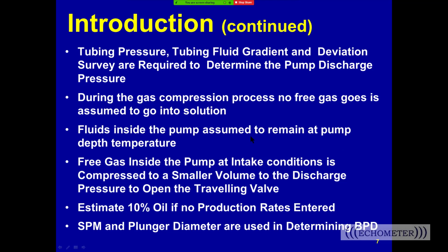We also assume for thermal calculations that all these compression behaviors happen at the temperature at the pump, and so we assume what we call isothermal. There's no heating of the gas that causes the fluids to change, and if the gas heats up during compression, then the gas temperature is quickly stabilized back to the temperature of the earth.